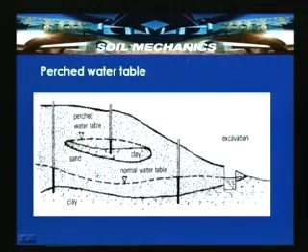There are also some situations like localized pockets of water table which can be possible when there are lenses of clay. Those types of water tables are called perched water tables. That is what is shown here, a perched water table condition. This is the normal water table, but this could be the localized condition where the water is under perched water conditions. So, it is called a perched water table.